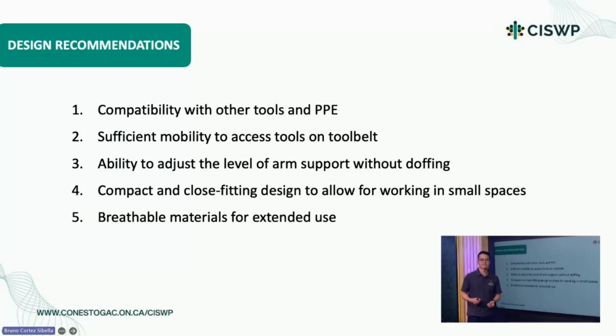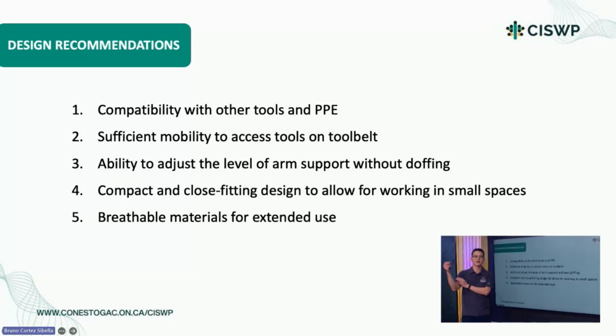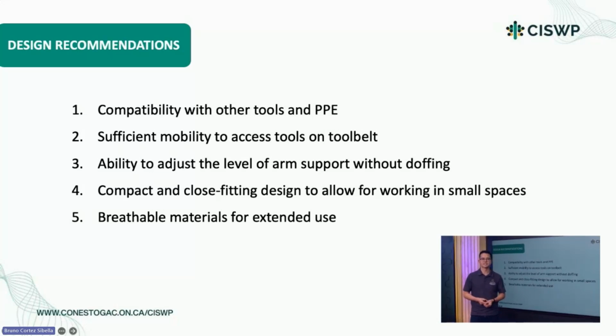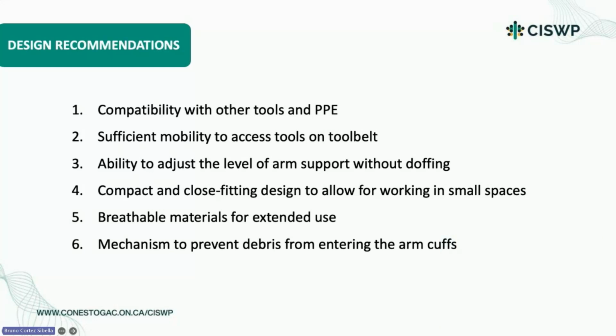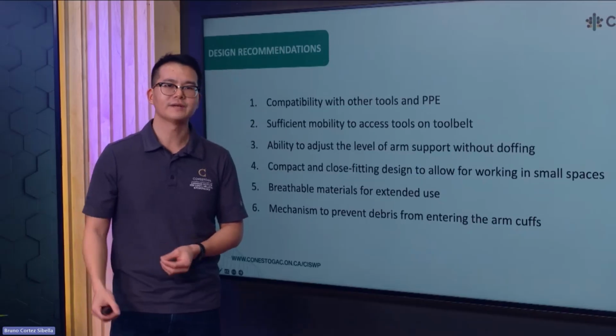So a few of our participants actually reported skin irritations where the arm cuffs were, even though we laundered the padding each night. This was particularly evident amongst those working in warmer environments, such as outdoors during the summertime or in heated work sites. Lastly, participants wanted some type of mechanisms to prevent debris from entering the arm cuffs. Since workers were cutting or drilling overhead, debris was falling into their arm cuffs, and workers had to repeatedly take off the cuffs, shake out the debris, and put it back on.